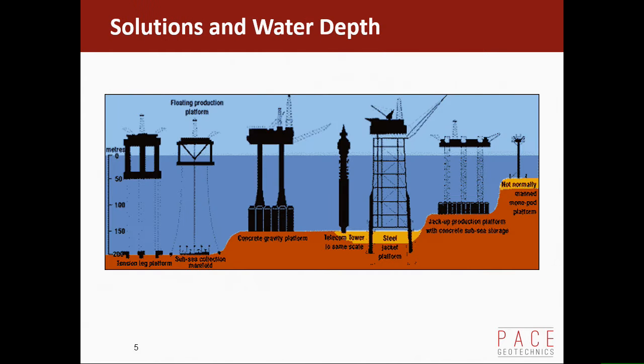These are some of the solutions you might see. I know it's focused really on structures which actually come through the water column, but it's applicable anyway, and it's good background. If you start at this end, that's basically a monopile, a steel tube hammered into the seabed, with a small platform put on it, which will just have a compressor station or something like that, and some control system. It would normally be unmanned. It wouldn't be big enough to be a manned position.